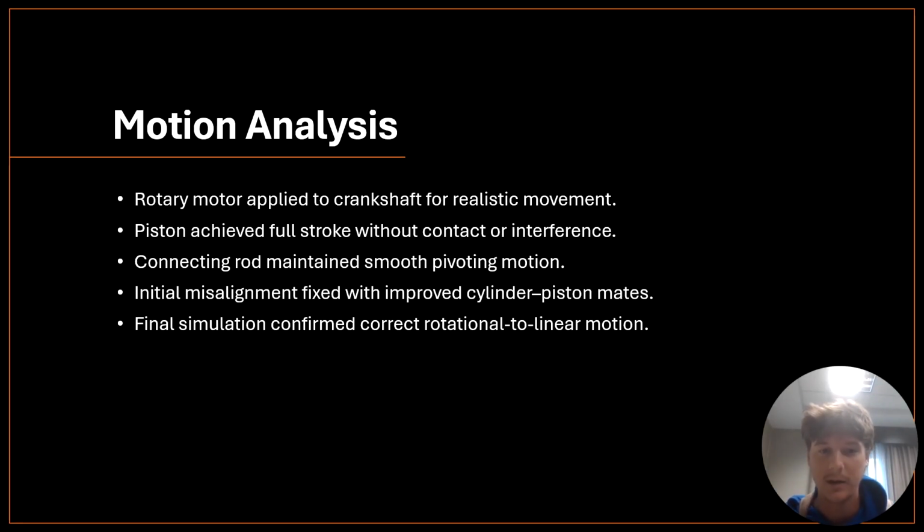So this is a motion analysis. Rotary motion provides the crankshaft for realistic movement. Piston achieves full stroke without contact or interference. Connecting rod maintained smooth pivoting motion. Initial misalignment fixed with improved cylinder piston mates, and final simulation confirmed correct rotational to linear motion.